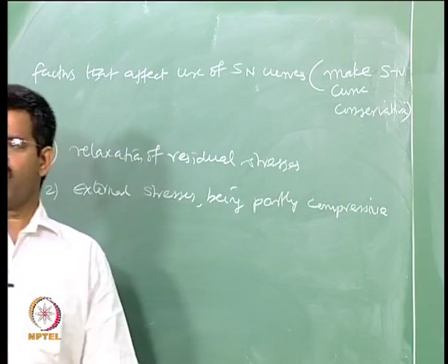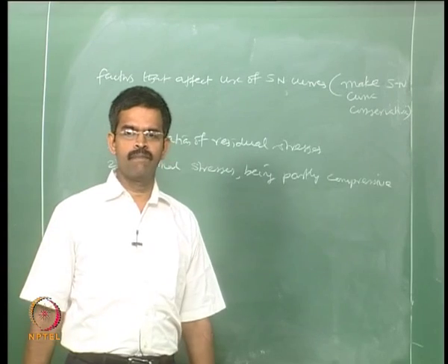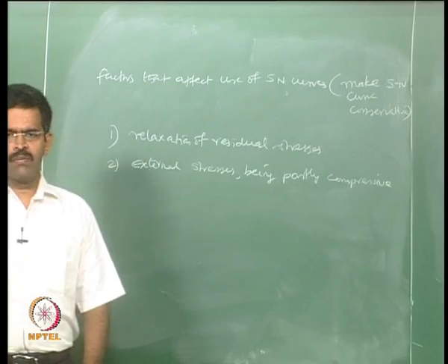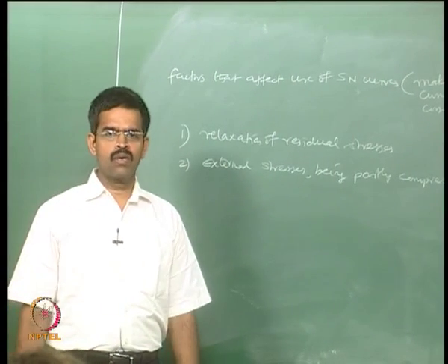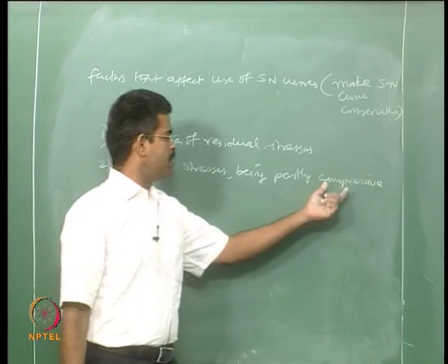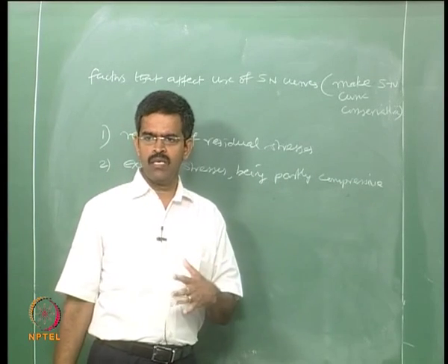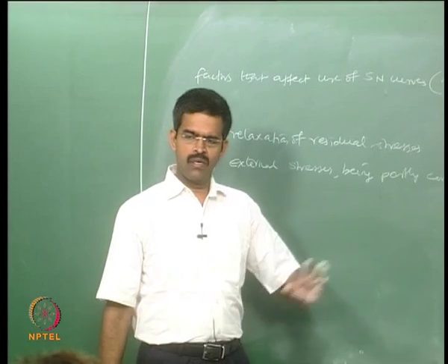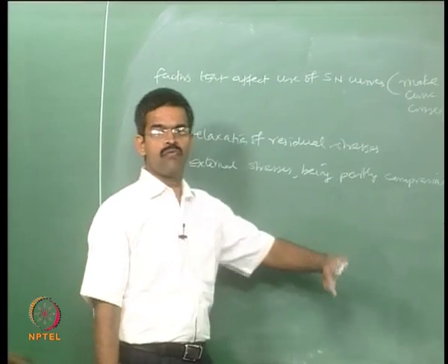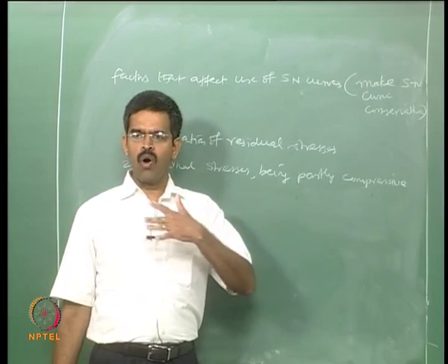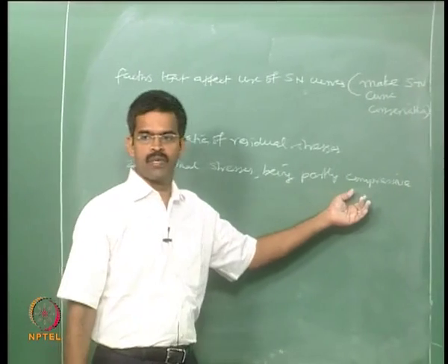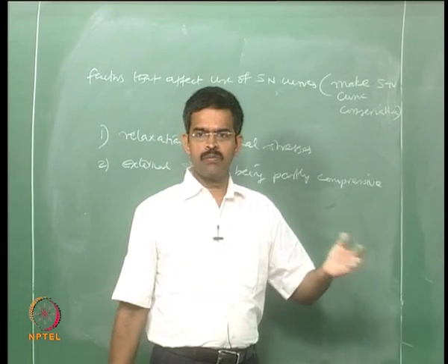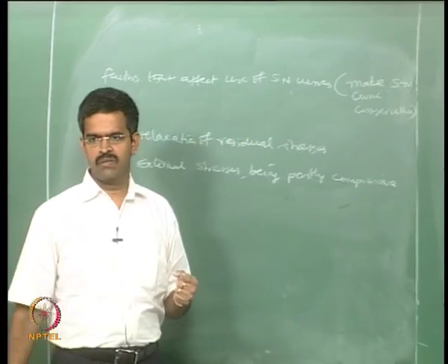See, whenever a crack is formed or initiated, if you apply further tensile stresses, there is a probability that the crack will get propagated or extended. When you apply a partially compressive stress to it, the propagation of cracks will not be as fast as that of a tensile stress. In reality, there is always reversal of forces. So, the stress does not remain always tensile, it can also become compressive. Therefore, SN curves which are plotted based on purely tensile stress ranges will become conservative.